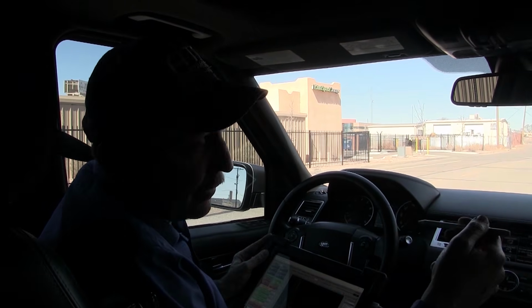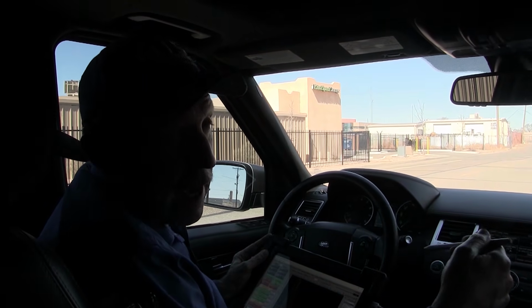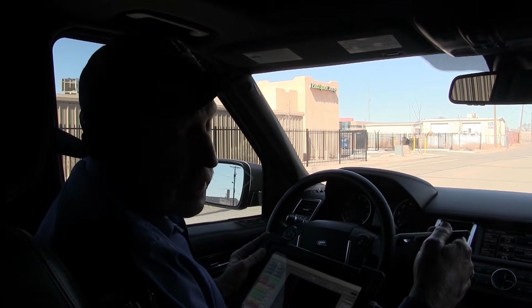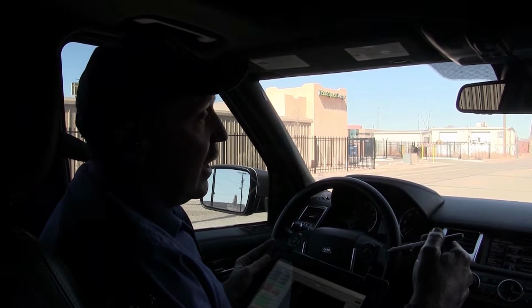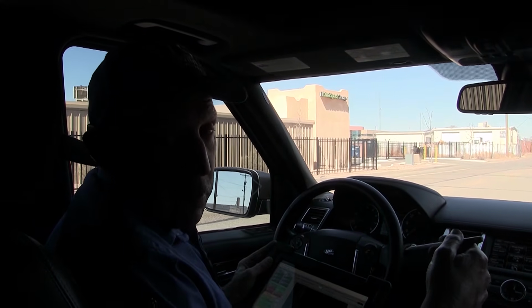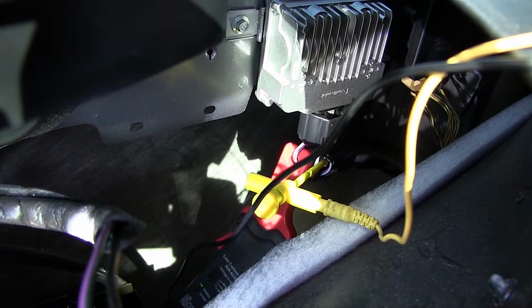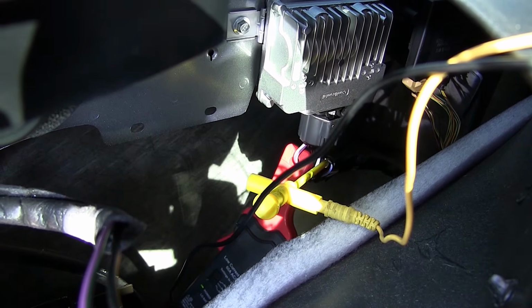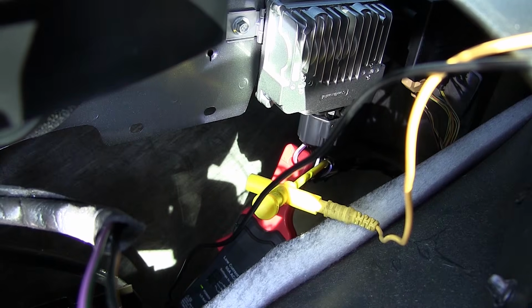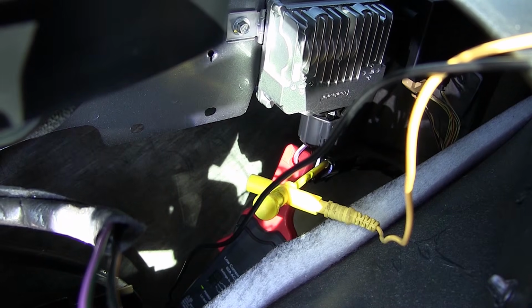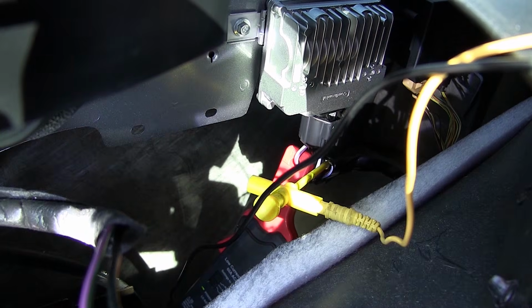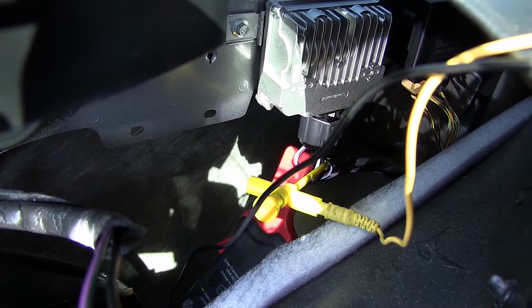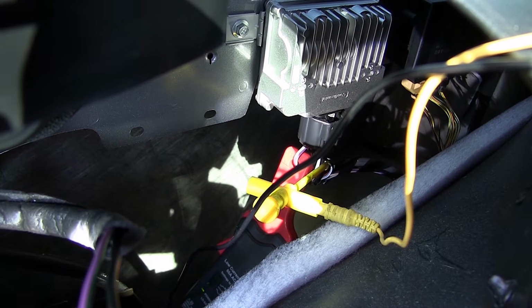But the problem on this car is it's in the fuel side, and we're definitely losing high rail pressure, and that's going to give us our problem. So let's try to figure out why we have that fuel pressure problem. This is the primary pump control. This is the pump that is in the fuel tank and drives the fuel to the engine. You can see that I've got an amp clamp on it, and I'm into the control wire that gives me the duty cycle, so we can see how much command we're trying to make up out of this low pressure system.